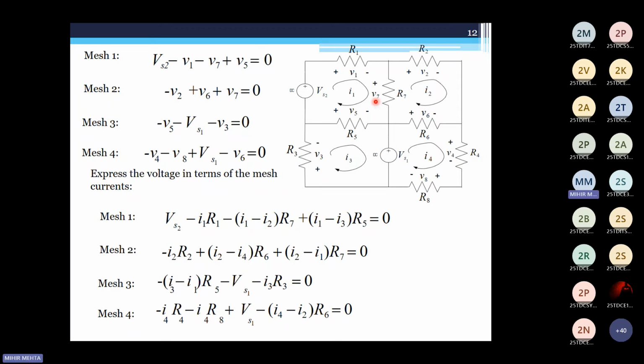Similarly, if we talk about the voltage drop here, since there is only one current here, that is I2, flowing through your resistance R2, simply it would be I2 into R2. And since my V2 is negative, I have my negative sign here, and V2 is nothing but I2 into R2. Similarly, talking about the current through this particular resistance R6, the loop is moving in the clockwise direction. And if you look at your current I4, again, it is moving in clockwise direction.